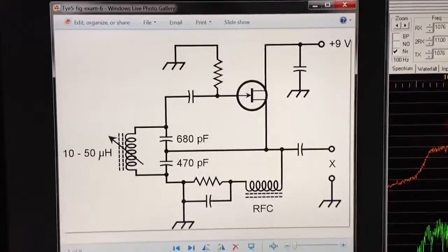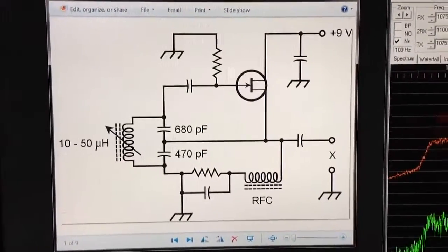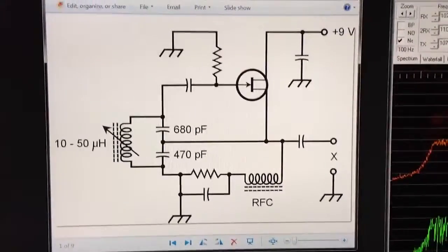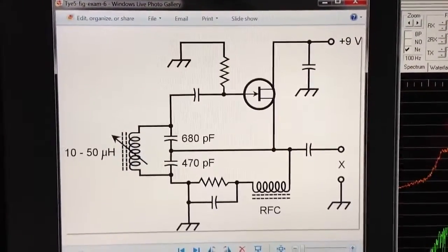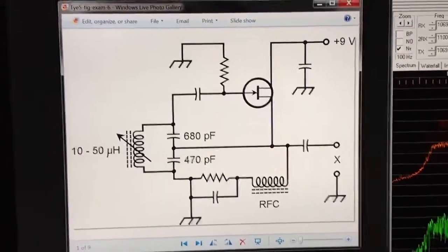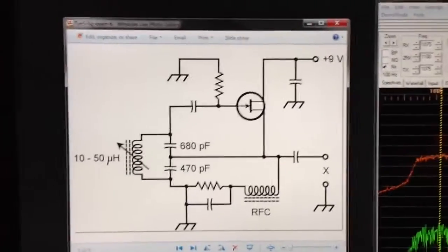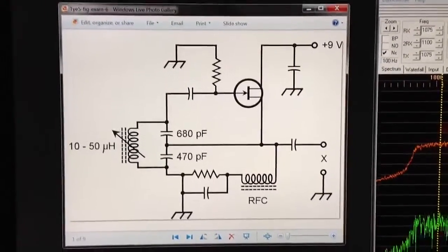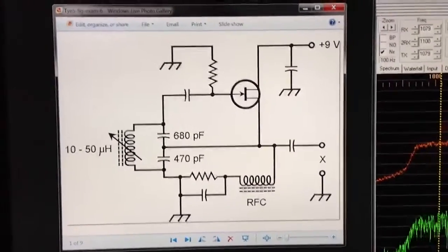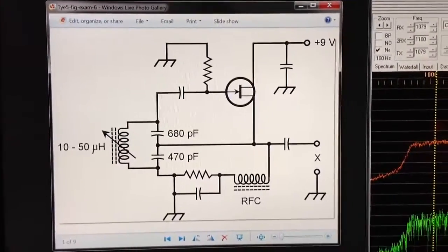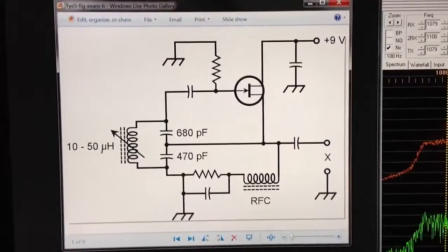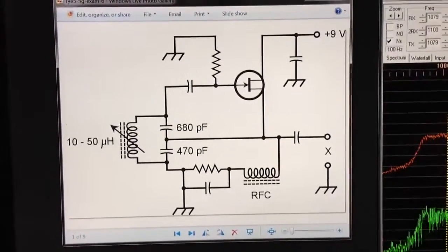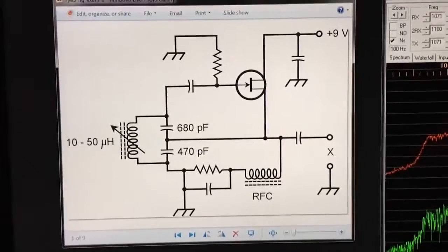Well, we already know that this is an oscillator circuit from the previous question, although if you didn't know that already, you might have a little more trouble answering this question. However, because this is an oscillator, a Colpitts oscillator in particular, because of the split capacitance, that's how you can recognize it, we get an RF signal, an unmodulated RF signal at the output terminals marked X.